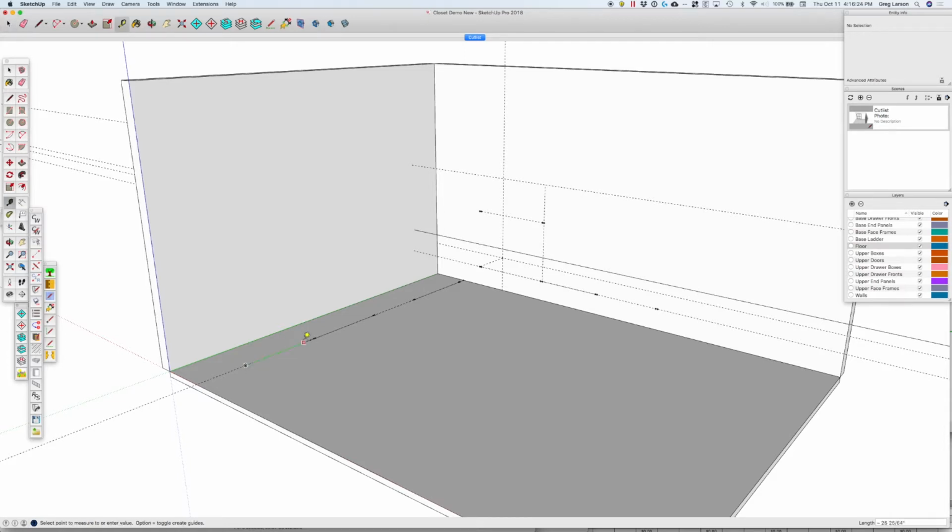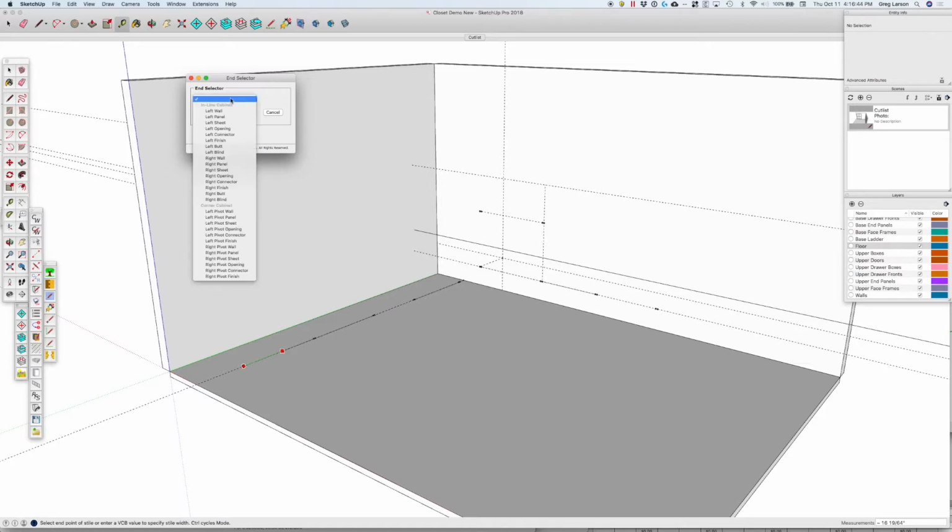So let's try that. So this first bay I've laid out on the floor here, I think it's something like 30 inches wide. Yep. So I'm going to go to my story stick tool, and I'm going to lay out the first one starting on this edge. By the way, we've set for a completely frameless setup here so that we don't have any face frames getting involved. So I'm going to do left finish, which means it's going to do nothing special to this end. It's just going to be a simple end.